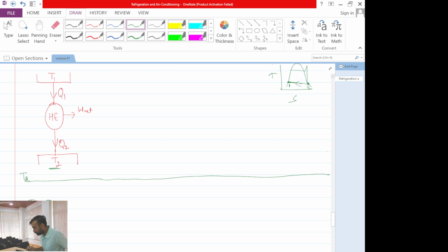In this process 4 to 1, what happens? Saturated vapor is converting into saturated liquid. Internally phase change is taking place upon removing the heat, so it can take place at constant temperature. So it means the process will be internally reversible, if the other working fluid to which it is removing heat is at some lower temperature. Is this one clear? All are clear with this idea?